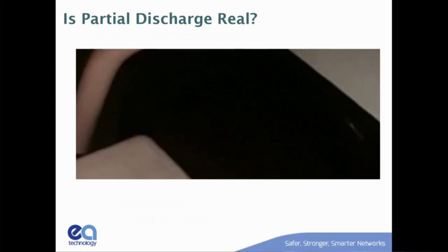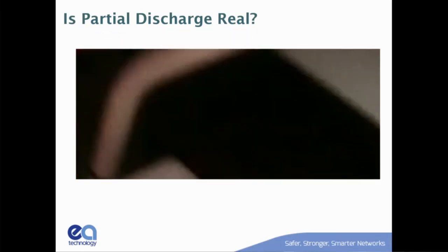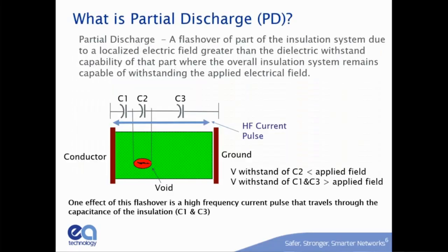As I said, if you look at this video, you'll see some real sparks. You can see it's intermittent, it's coming and going. That's partial discharge. And if you could stick your head inside metal clad gear, you would see that. Now that's pretty severe, but I've had customers that couldn't locate the partial discharge to a specific cabinet in a lineup. So they took the cap off the end of the bus bar section and looked down the bus bar section at night in the dark, and you get little blue sparks on all the insulators holding up the bus bar. Now, that's not a very practical way of finding PD, but it is there.